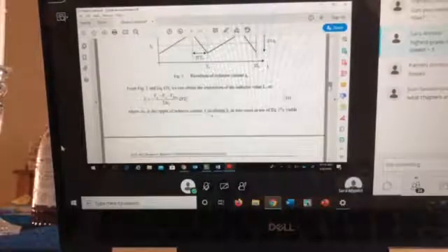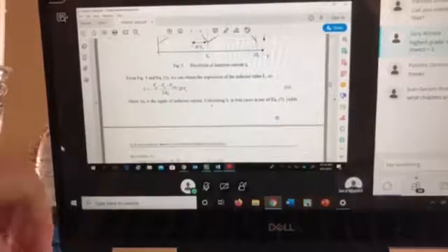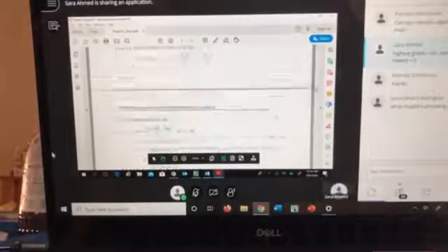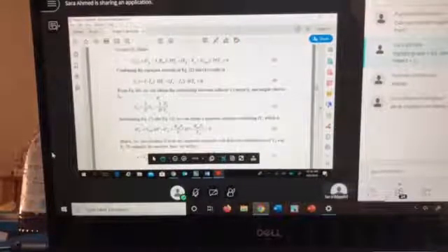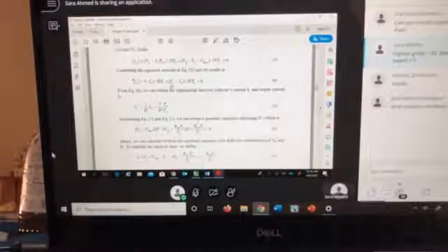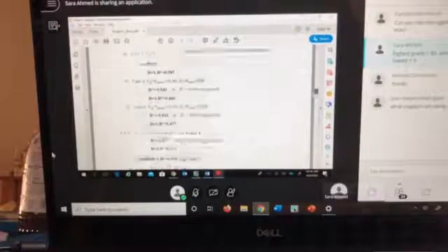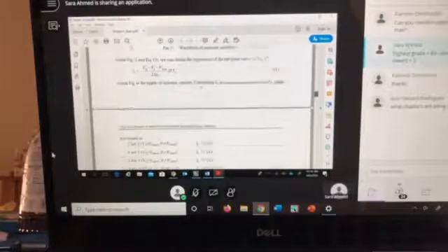Okay? So now, what's my concern? What do I know? I can find my I of L. How did we calculate the I of L for all cases here? You calculated I of L for all cases by your capacitor charge equation that we derived in here. When we put the I of C average to be equal to 0, then I was able to calculate my I of L. So this is the steady state I of L, which I need now for my inductor value. Why do we need it? Let's look at this equation.